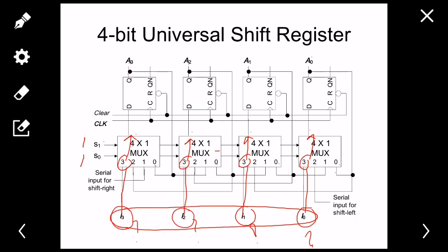Now see that this is a very simplified connection. We just made a simple connection of port number 3 with the inputs. So in this manner, see what will happen if I give input of 0 at this point: this 0 will travel to this point. After a clock pulse, this 0 will travel to this output. So this will be happening in a parallel method.